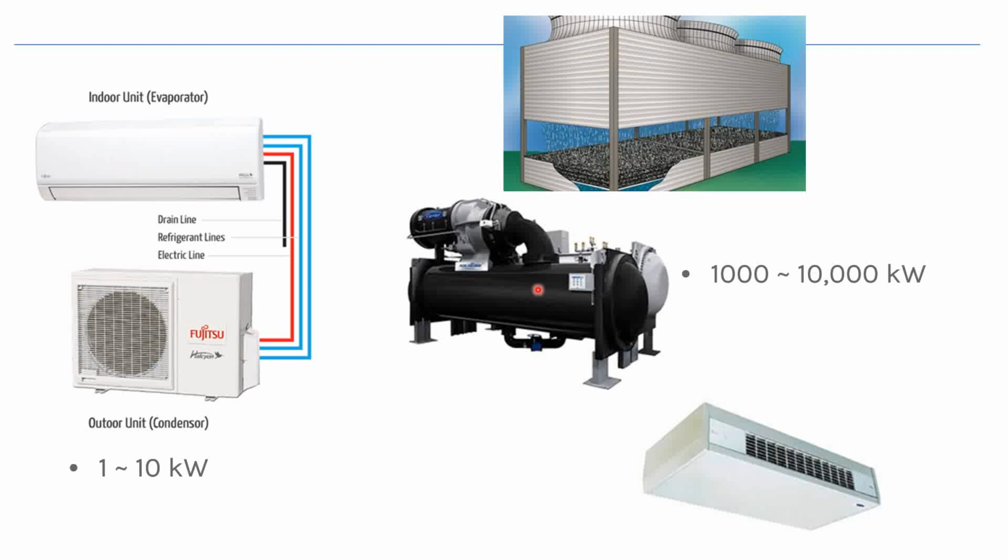So the refrigerants take away the heat that's being absorbed from the indoor environment. So it's another part of the heat exchanger. And because it utilizes refrigerants, later we will learn that it involves boiling and condensation. So it's very important that we know how to calculate the amount of heat that's being taken away, both from the indoor environment and also the heat exchange in these chillers.